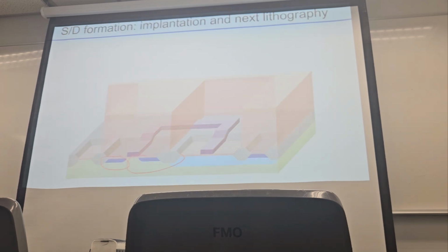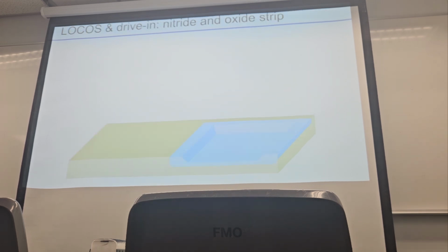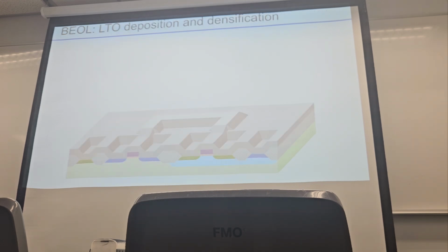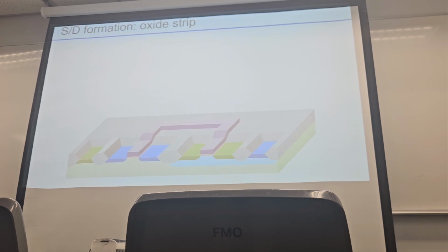Okay, so you can see that to guarantee the quality, we need to do multiple oxidations. You can see how many times of oxidation we have done: one, right, and second, we have done two times of thin film silicon dioxide to guarantee the quality. Okay, and we use the PR for the implantation.